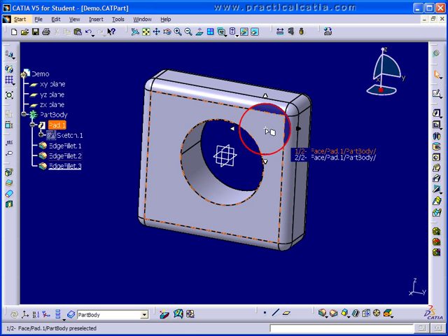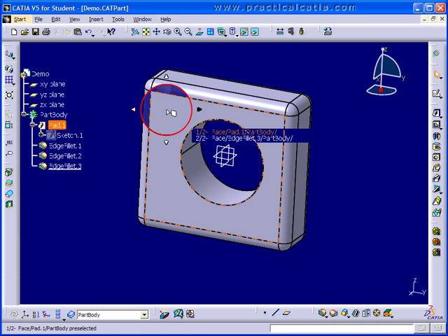and it will select through the part. And wherever it sees a face, wherever it's coming in contact with a face, wherever the cursor's at, you can select that face. Like for example, I can select that back fillet right now. If I select the up arrow key or down arrow key on the keyboard again, it's going to give me another selection. That's the front face. And then that's selecting actually behind the part. I'm not sure how useful that is.